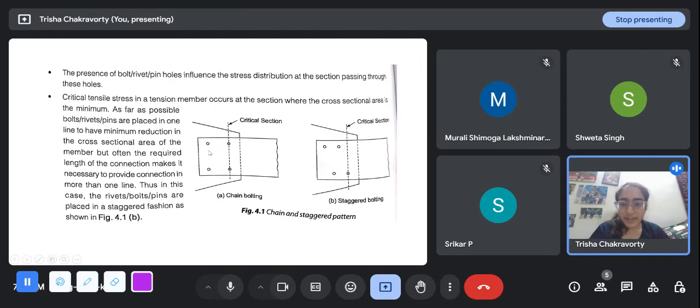So the number of bolt holes along this line is what will keep on making it more critical. So we would try to get it done by one line of bolts along this, but that is not always possible, because for connection design, we have already arrived at a connection design with other criteria. So suppose this is the connection arrangement that we have reached.